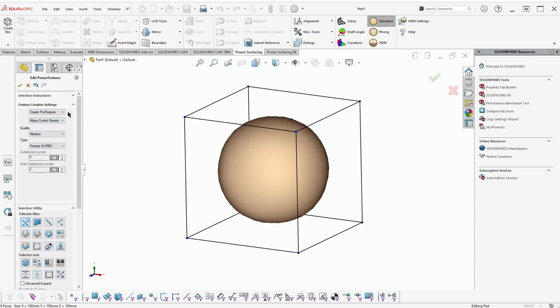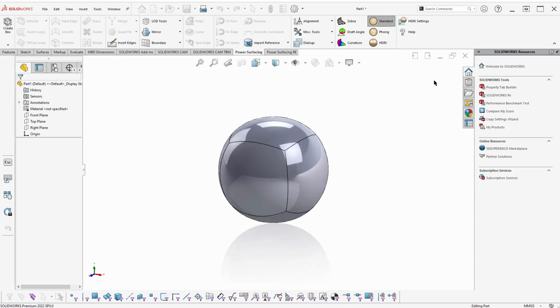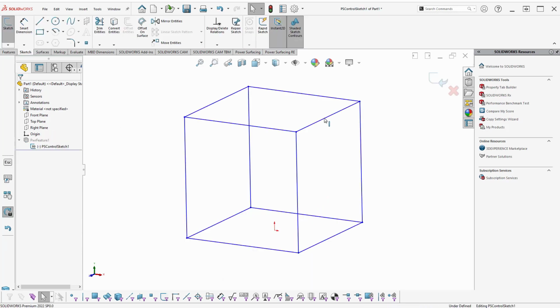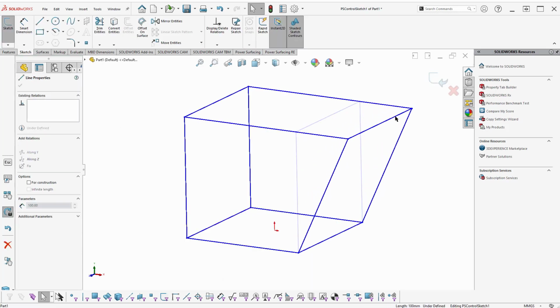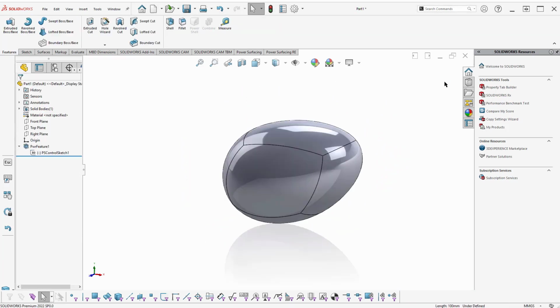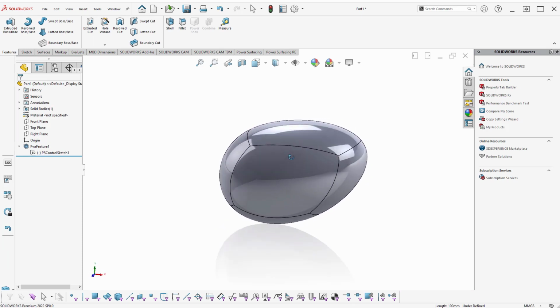And now from now on, unless you change this, you will have a control sketch which corresponds to this object. In order to get that though, you have to convert it one time. Okay, now we have it. So here we have a control sketch that we can edit. And for example, we can move something here. And when we say OK, you can see it's updated the underlying sub D.